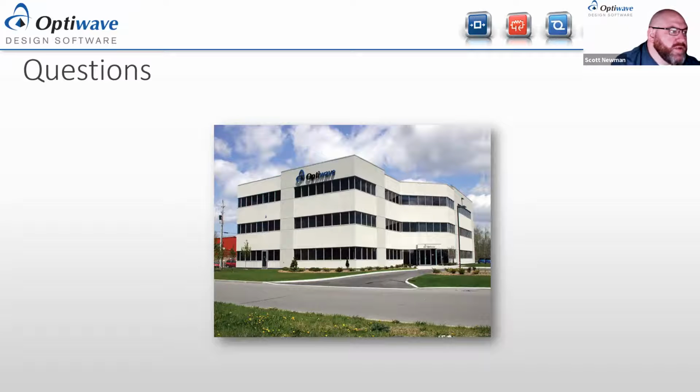The next question we've got here is, under what circumstances would a researcher use one of the Q factor calculations over the other one? So for example, as I said before, the spectrum one is the standard definition and it's the one people used to use the most. The problem with it is the mode needs to decay enough for you to capture that information within the spectrum information, right? Because as your mode decays, it's going to become more and more of a Lorentzian. And you need it to be at that state to get the correct information for the spectrum analysis.